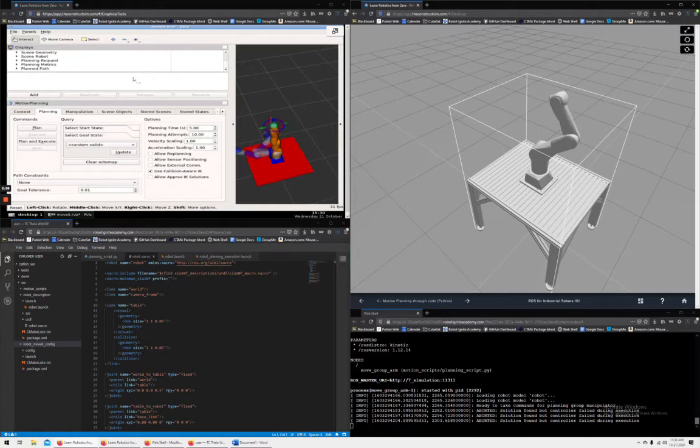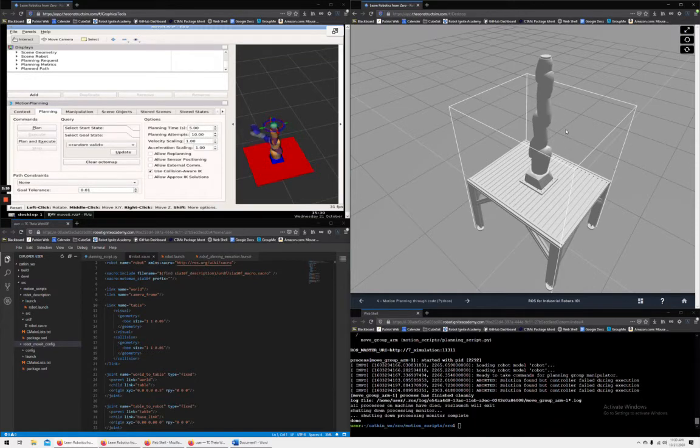values. By setting different plans for the group here of the arm within MoveIt, I was able to assign different locations within the trajectory or within the joint space for the robot to move to, still displaying some of the functionality that it would use if tracing those characters, if tracing alphanumeric characters.